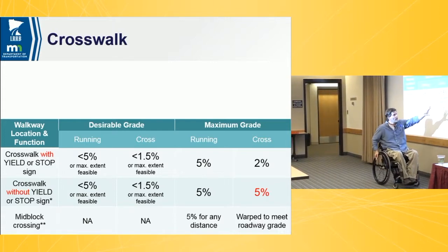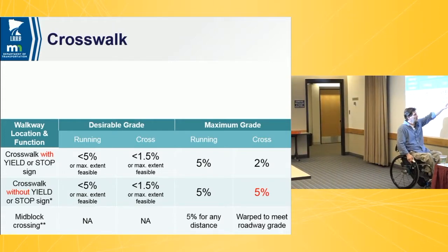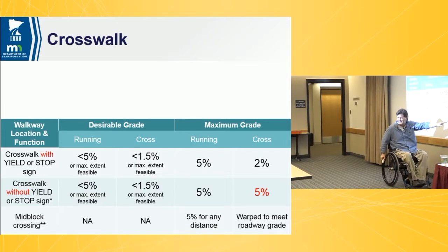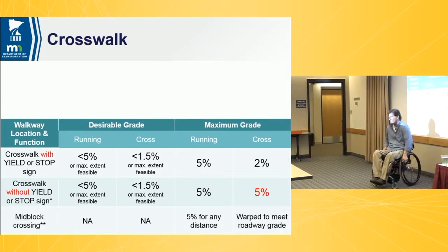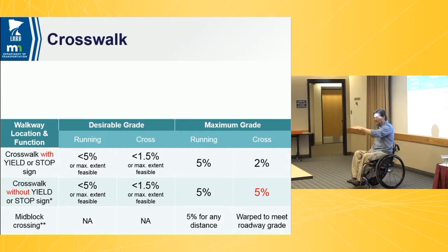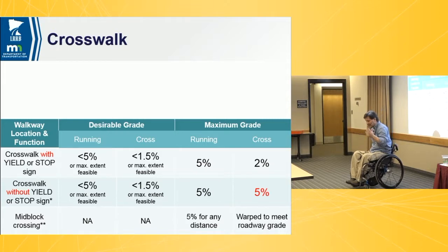So I'll go over to PROAG here, and they'll talk about the running slope. You can see is always 5%. So that's the crosswalk running slope as you're going up and over a crown. So it's your crown, your roadway cross slope. So that's a 5% maximum, just like it is for a sidewalk. That's what your crosswalk can be. So anytime your shoulder slopes or your highway slopes are over 5%, that doesn't meet standards. So we're looking at that.